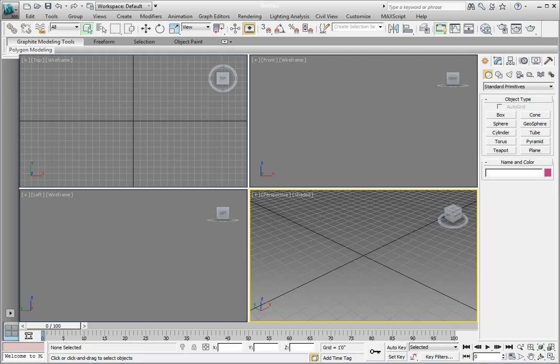This is where 3ds Max and the use of the Link AutoCAD feature can become a critical part of a successful design visualization campaign. In this lesson, we are going to use the Link AutoCAD import option to create a live link to an external AutoCAD file.